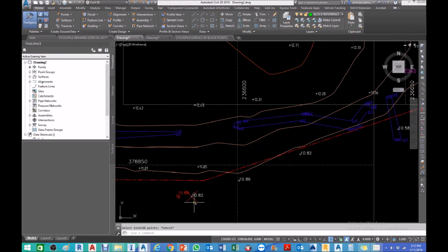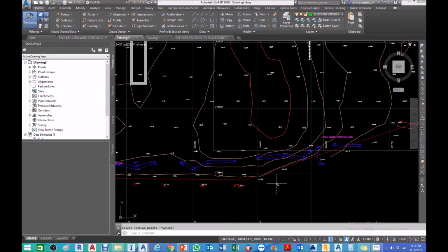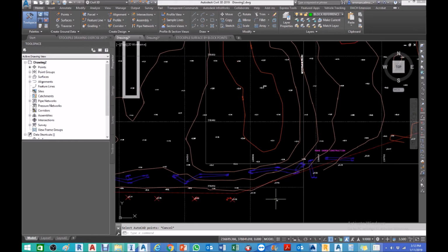And the problem again, there's no coding. Also, sometimes the contractor or somebody will give you a CSV file, but the coding is not good or there's no coding. Huh? So they will tell you, no, that's the only thing we have. It's NGL points. Yeah, it's NGL points, but how will you know if there is a sudden change of terrain? Okay, meaning it's still like a mistake if there's no coding.